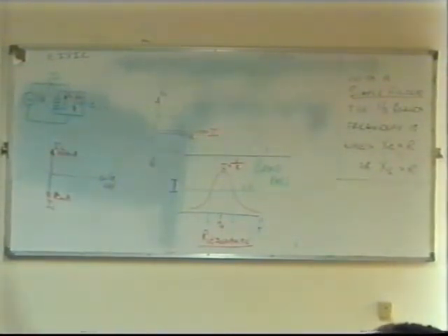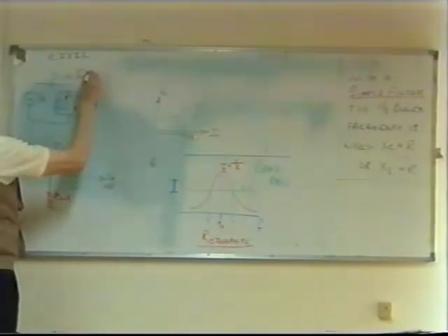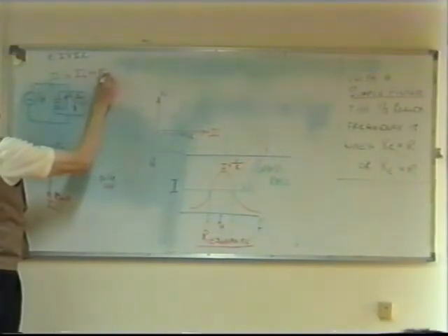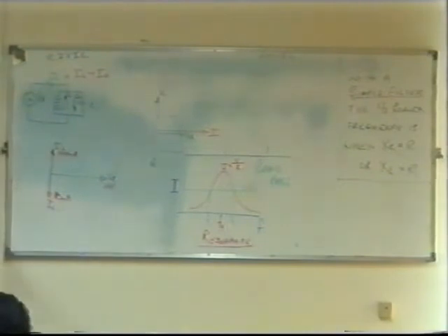What if you put some resistance inside? We'll not put the resistor in at the moment, just currents. So IS is actually equal to the difference between IL and IC. This little symbol here means difference between. Whichever one is bigger, subtract the smaller one from it.